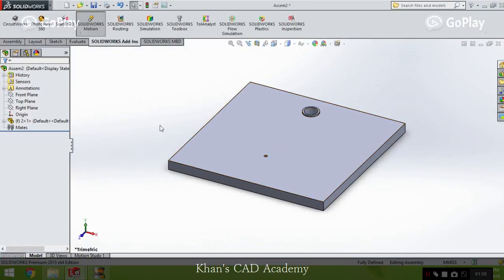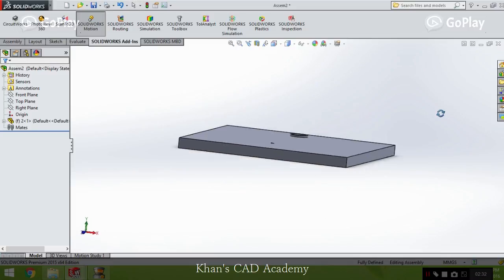It's the base. Keep in mind, those parts which you do not want to get into the motion, you must select as the base or the first object, else they will not be animated. If you select the base part in the second or third position, it will interfere with the animation and they will not animate. So it's advisable to choose the part which is not included in the animation, so choose it as the base part.